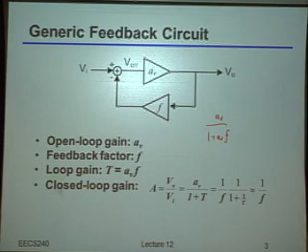Now again, just as a real reminder, if you really think about what feedback buys you, there are lots and lots of benefits that people quote. But at the end of the day, the only thing that really is a fundamental benefit of feedback is that it basically allows you to set the closed loop gain very precisely. Everything else, it turns out you can actually get just as well from an open loop amplifier. So the real only benefit is it allows you to set the closed loop gain.